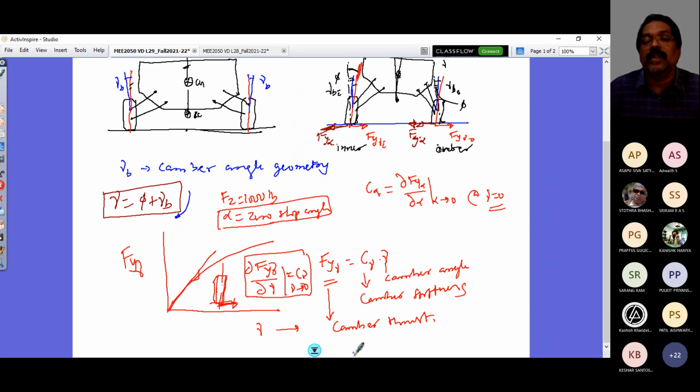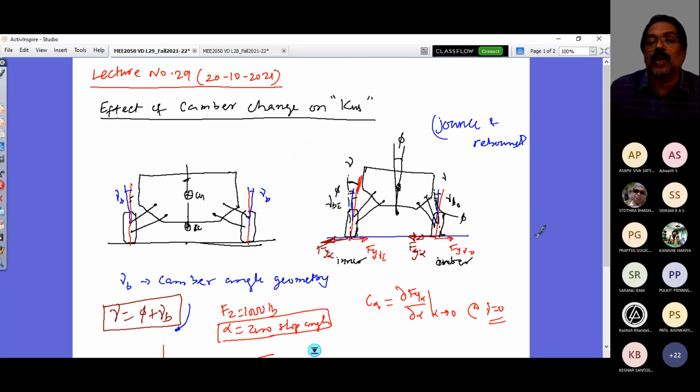So you get added. Now there are three terms that come. You may wonder what happened to lateral load transfer here. I'm not accounting for the lateral load transfer and the roll at all. I can map what we did in the last class along with that. That's what I was telling: the free body diagram is drawn for the requirement of forces only in that context, right? You have studied in rigid body mechanics that I have a system of forces maintaining dynamic equilibrium. I can divide that system of forces into sets of forces for individual dynamic equilibrium as well. A free body diagram can be represented like that. So we just take it for the context and look at the required forces.